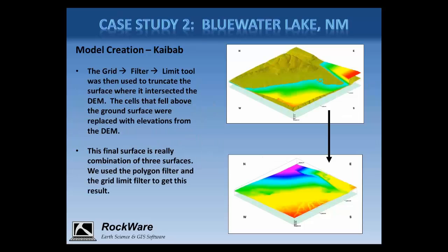Now, I mentioned previously that when we created additional control points using the measured bedding information, we chose to create control points both above and below the current ground surface. And we did this because we found that it is typically much easier to create a realistic subsurface grid if it is reconstructed above ground as well. This also makes it much easier to create surfaces that intersect mapped geological contacts.